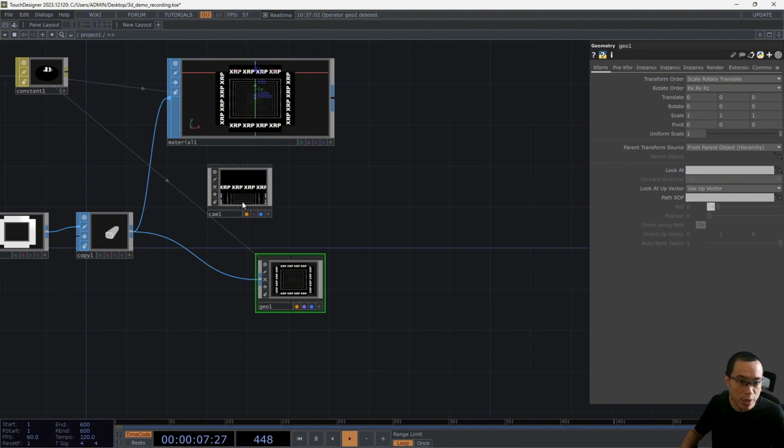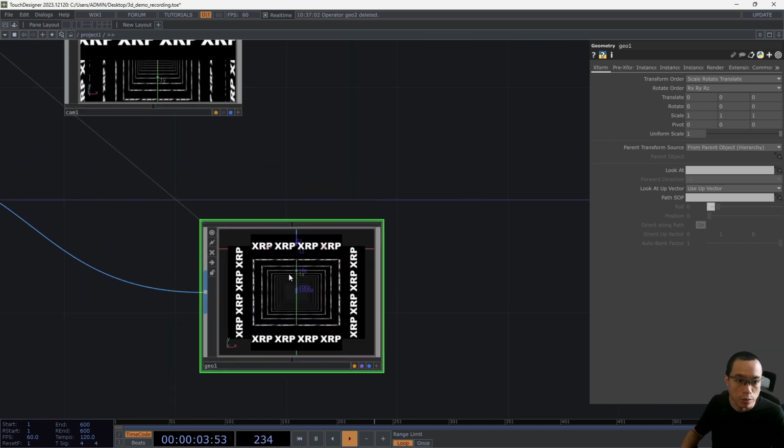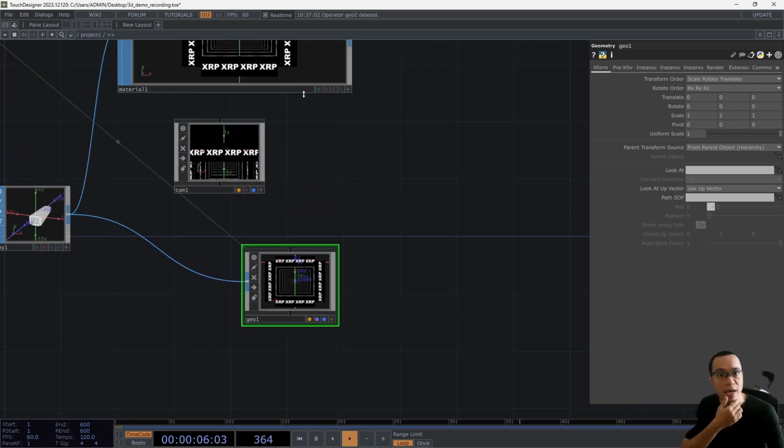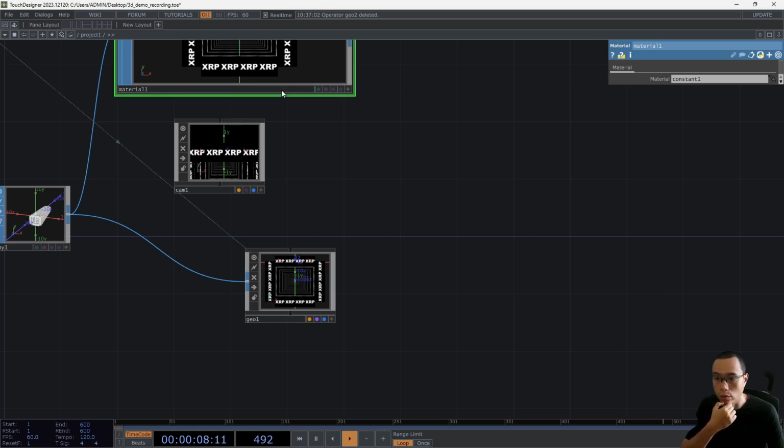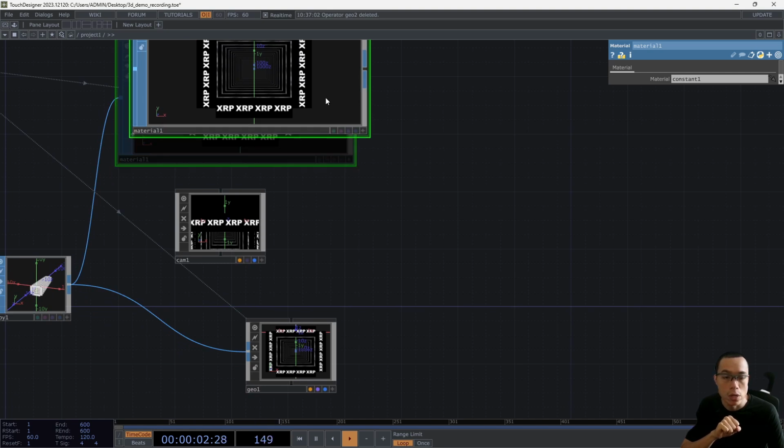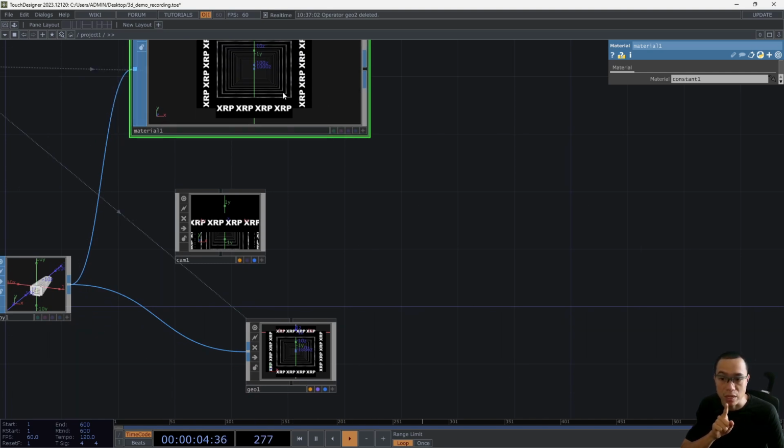Click on it, and basically it's going to map the material on the geometries over here. Now you wonder why the material soap is available. The material soap is a very quick way for you to preview the mapping of a material on an object instead of setting all of this camera and renders, etc.